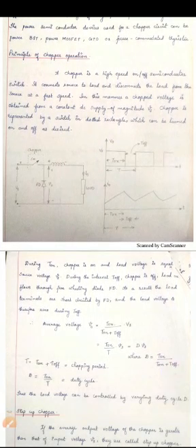So the figure here shows a step down chopper. Generally, a chopper is a high-speed on or off semiconductor switch. In the figure, you can see a voltage source V is connected on the left-hand side of the circuit, and is connected to a load. A switch, which is called the chopper, is placed in the circuit, and there is an inductor and a freewheeling diode connected in parallel. So this is a simple circuit of a step down chopper.